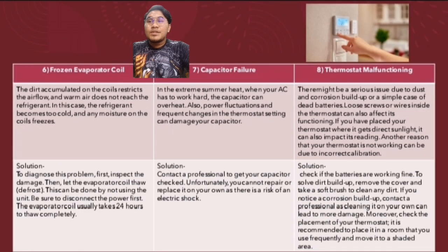Next is frozen evaporator coil. The dirt accumulated on the coil restricts the airflow and warm air does not reach the refrigerants.